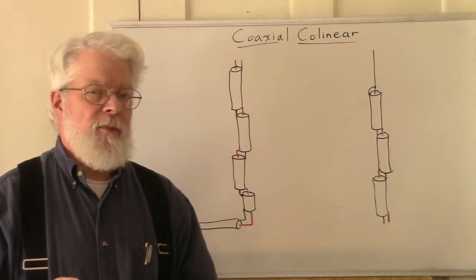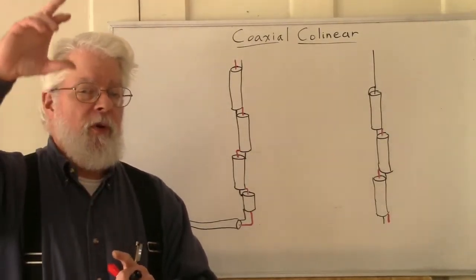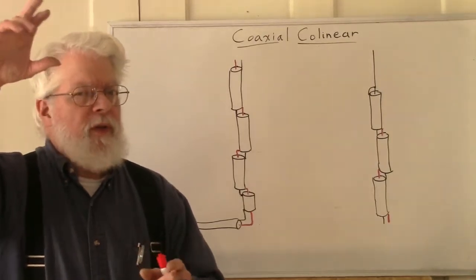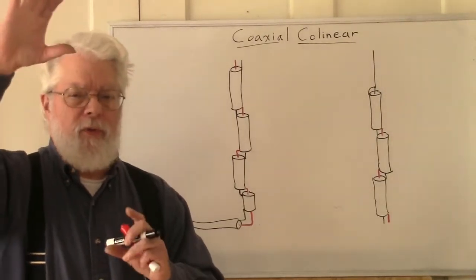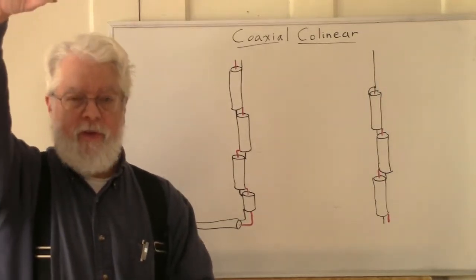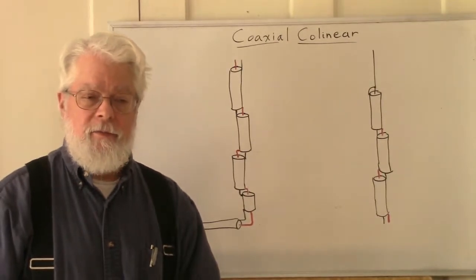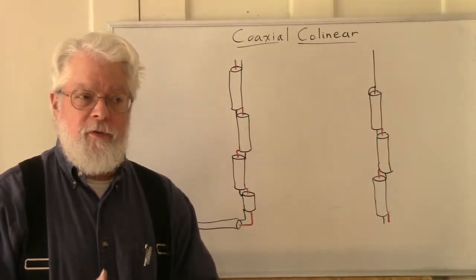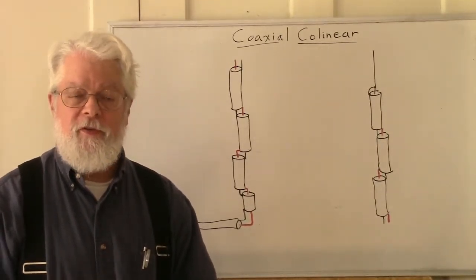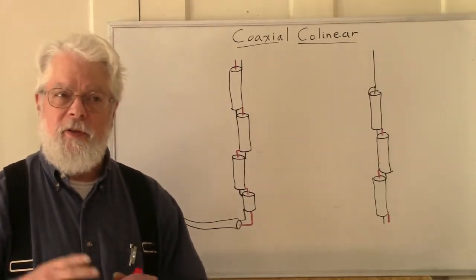This antenna is not so much. Each half wave element contributes almost equally to establishing the field, and having such a large aperture, it's very good at null fill. And if you've operated repeater systems using a Station Master, you'll notice they do tend to have a little bit less picket fencing, a little less dropout.